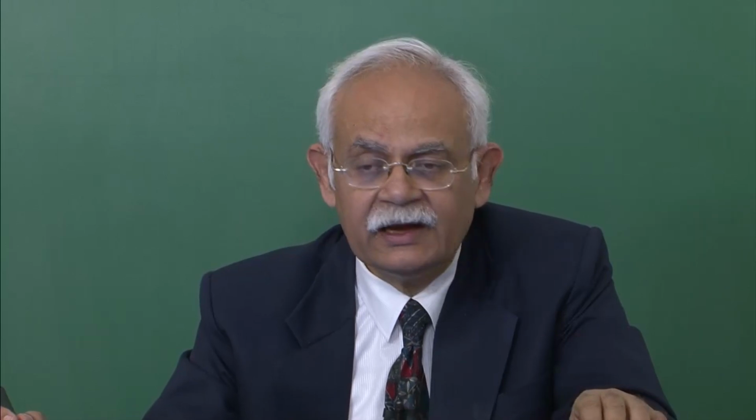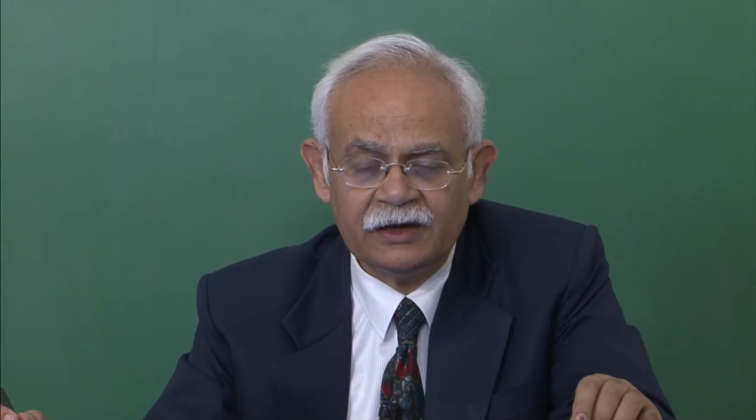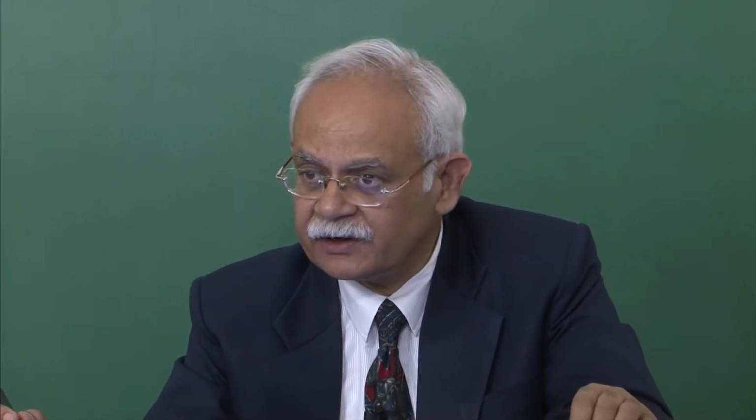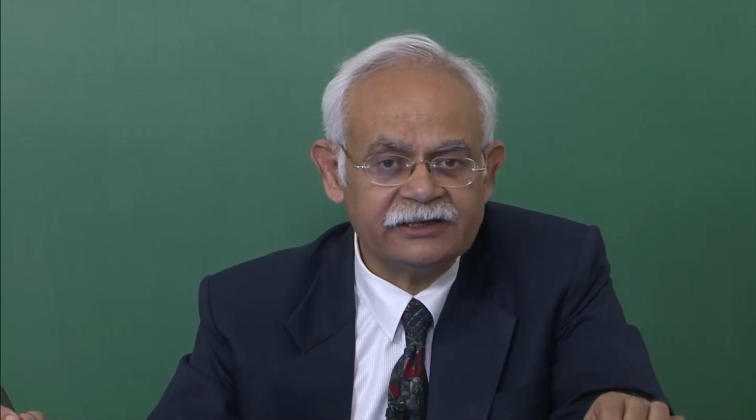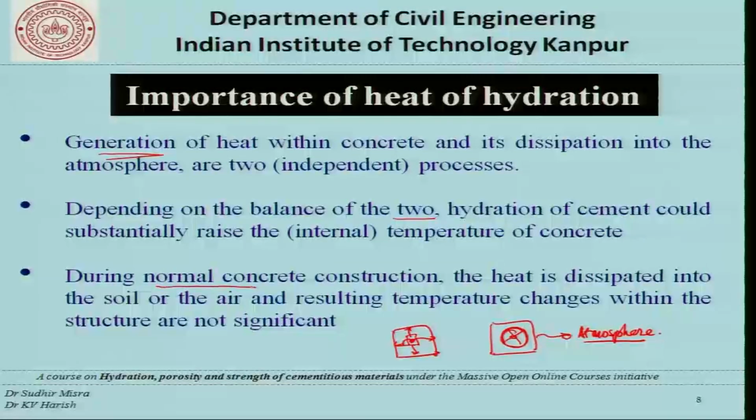Now, this difference between the heat evolved and the heat dissipated is important for us to understand when we talk of implications of heat of hydration as far as concrete engineering is concerned. In normal concrete construction, the heat is dissipated into the soil or the air, and the resulting temperature changes within the structure are not significant.